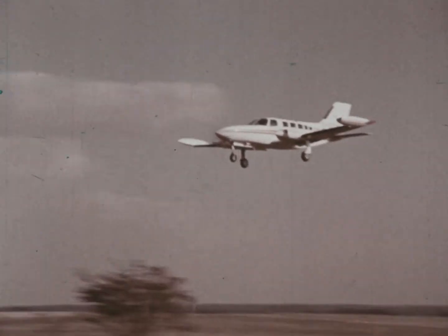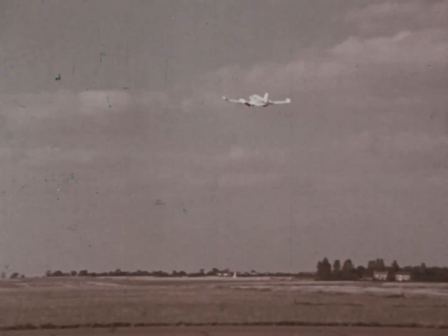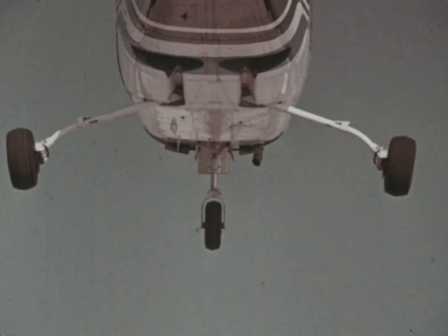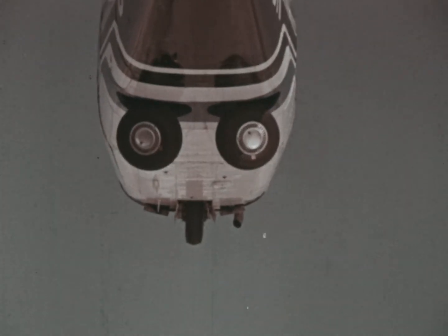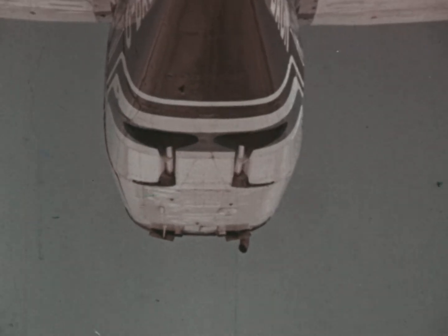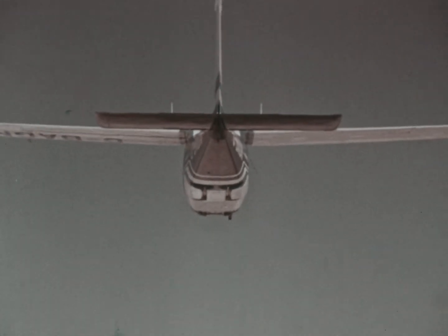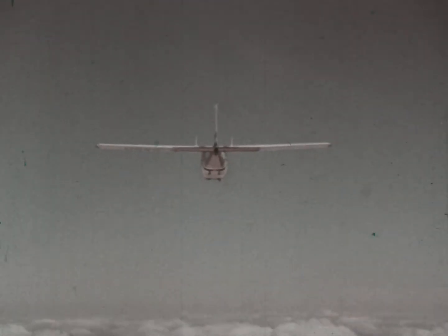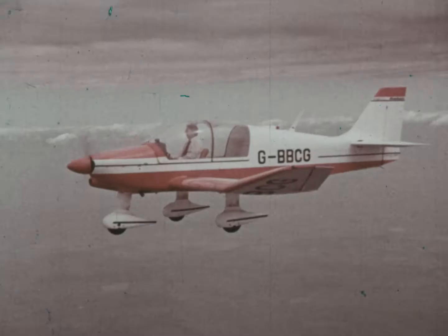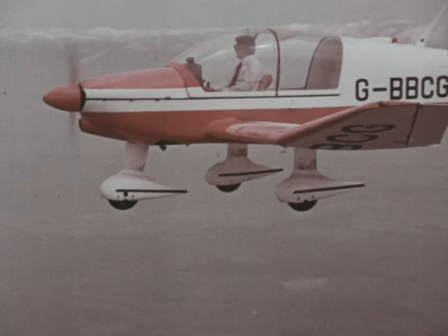One obvious way of streamlining an airplane is to give it retractable landing gear and eliminate struts. The results of cleaning up the form in this way are often worthwhile, both in terms of performance and fuel economy. But if the gear has to be fixed, then the answer is to streamline it along with the rest of the airplane.